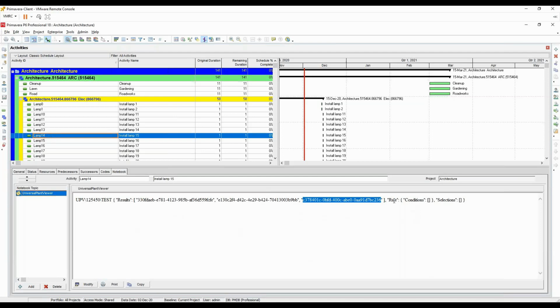As you can see, we also have a rule and a selections node here. So in rule, we could store conditions. For example, a condition to collect all pipes starting with a certain name or all equipment items of a certain area and so on. That would be stored in a rule. And then in selection, we could store the UIDs that were selected when the rule was applied.